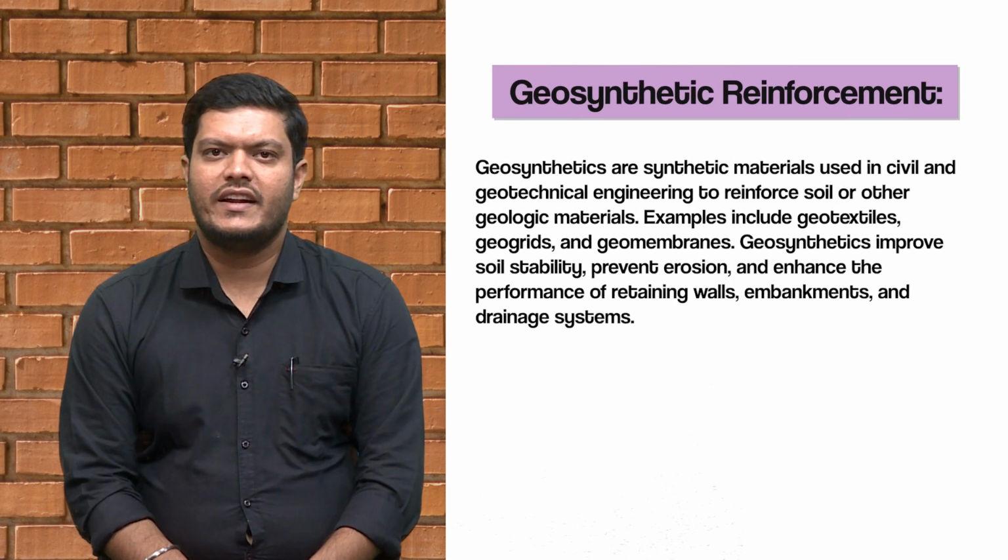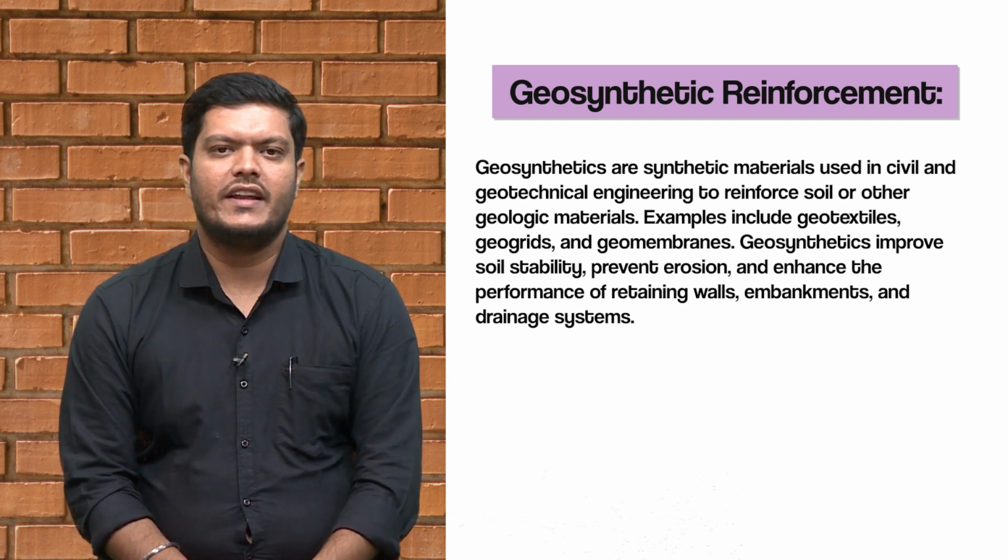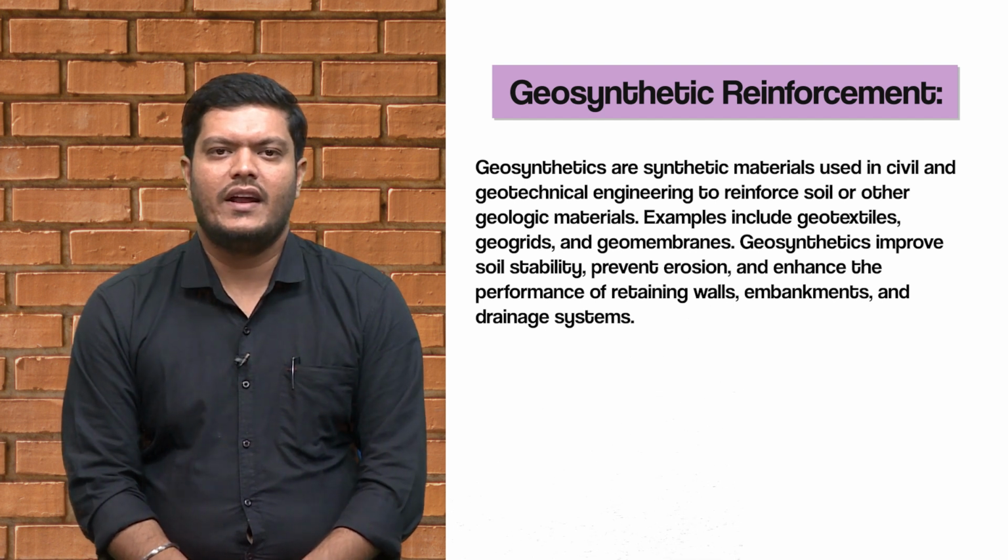Fourth, geosynthetic reinforcement. Geosynthetics are synthetic materials used in civil and geotechnical engineering to reinforce soil or other geologic materials. Examples include geotextiles, geogrids, and geomembranes. Geosynthetics improve soil stability, prevent erosion, and enhance the performance of retaining walls, embankments, and drainage systems.